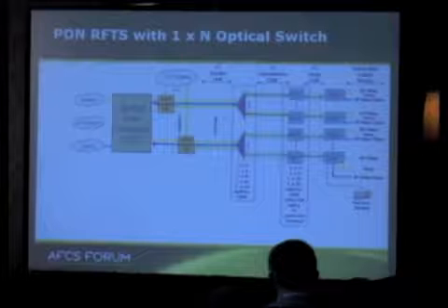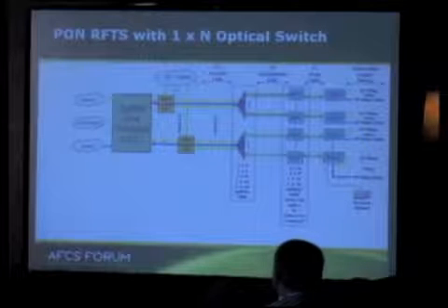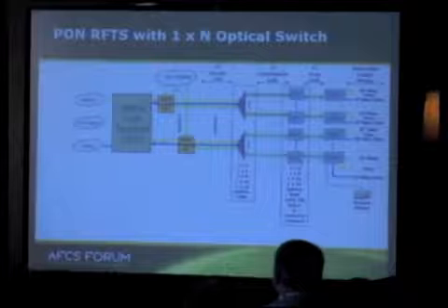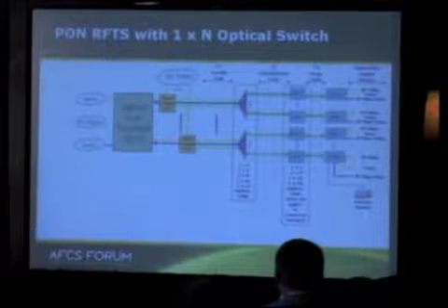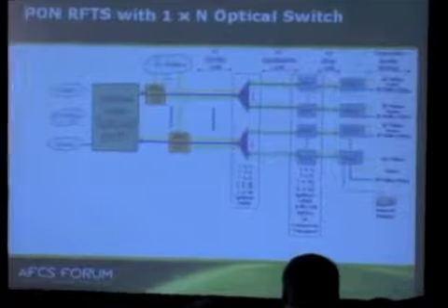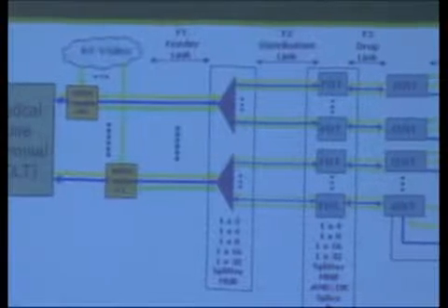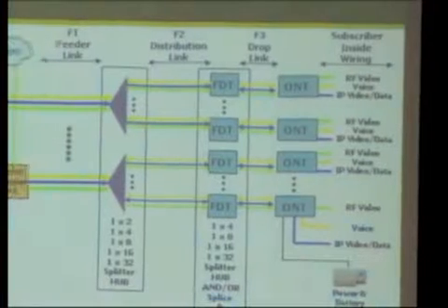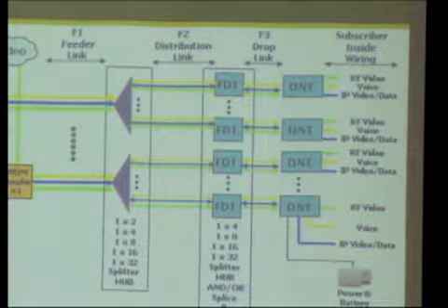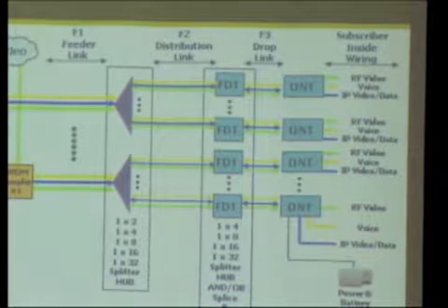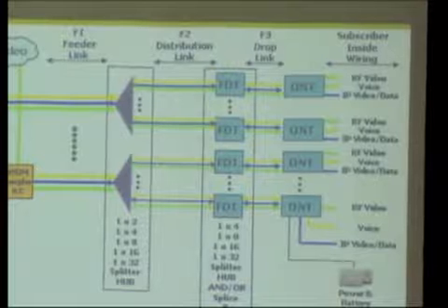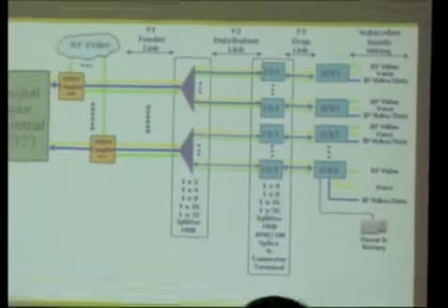Nothing unique there. Some people use multiple splitters. In a PON deployment, you can actually use up to 3. I haven't run into anybody doing that, but it is not untypical in Europe to use a cascade of 2 splitters, an 8x8 followed by 8x8s, for example. Verizon right now is thinking of, in their GPON, a 1x2 followed by 2 1x32s in the field. So there are applications where you do get into multiple splitters, and the big issue is, how do I find a problem between those splitters?